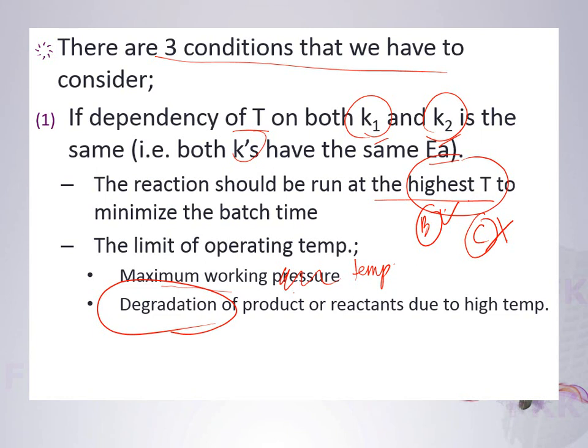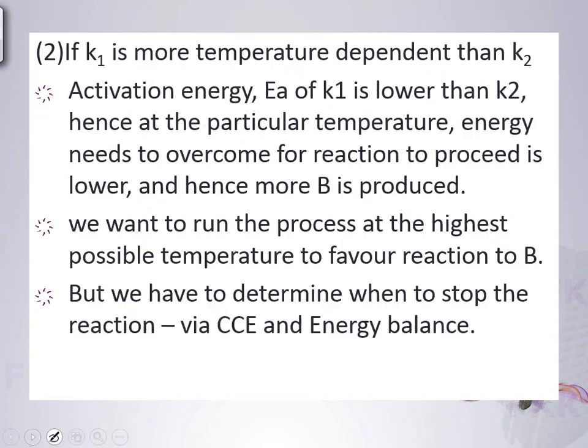The parameter that you can change, anyone? Pressure. Because when you decrease the pressure, the temperature will decrease. So you can always work under vacuum conditions. When you work under vacuum conditions, the boiling temperature will decrease. Then it won't affect your component, because the degradation temperature is lower than the component's temperature. Okay, that's one of the hints on how to do your DC.